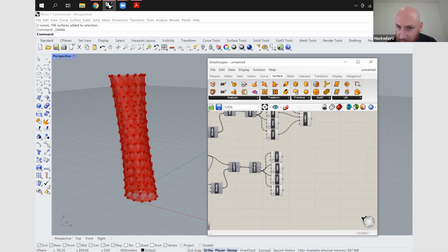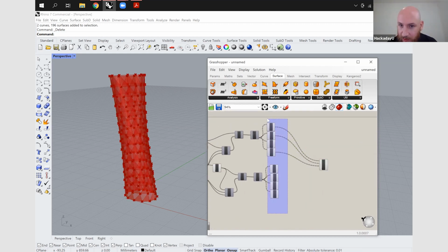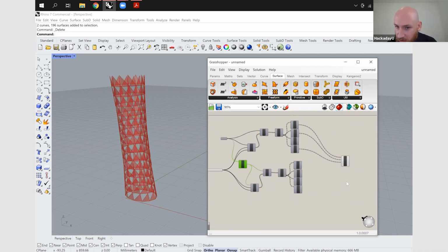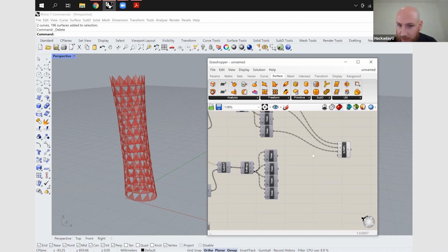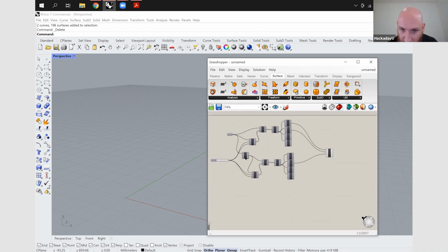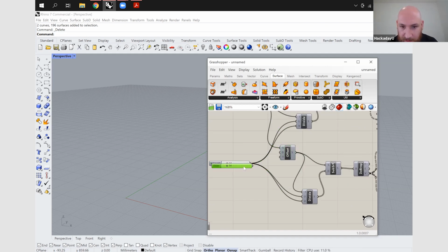And if I now want to create my 3 points, I'm just going to Control Q to turn off all those points because they're kind of in the way. And I can turn off this offset surface because that's the whole surface. And change one of the points of our three-pointed surface to be on our offset surface. And I must have done something wrong. Oh, actually, I know what I've done. I have no distance on the offset. So let's just give it a distance. There we go.